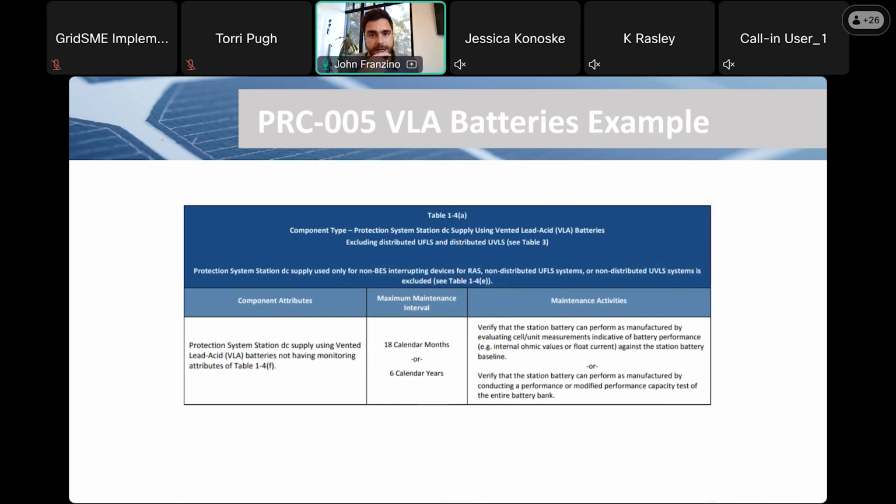Thankfully, since most relays these days are solid state relays, their time horizons are either 6 to 12 years. So while you definitely want to conduct and document your PRC maintenance at time zero, aka commissioning leading into commercial operations, to set that first date of maintenance, besides batteries in a modern substation, you're not having to do these verifications and maintenance activities all that frequently.